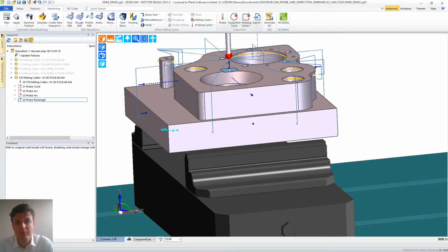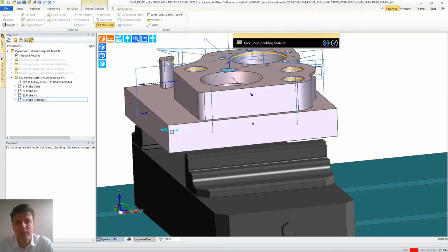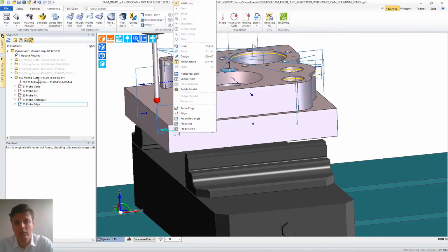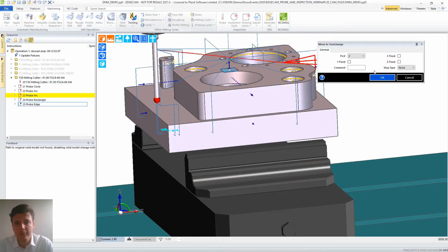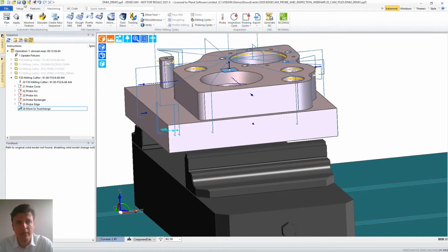So this machine does not support the plane, and it's not supporting the angled cycle. So again, if you have something similar, update your post-processor and then output an error to your customer saying, hello, remember your controller does not support that probing cycle.